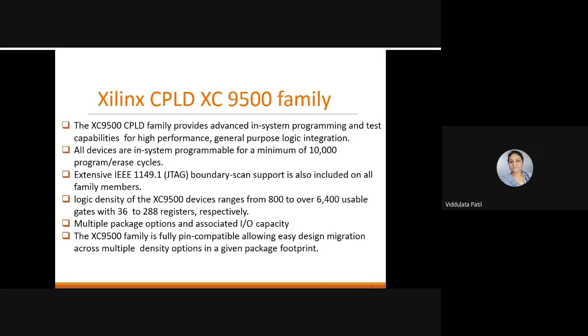This standard is supported by each member of the Xilinx XC9500 family. Because of that, it makes the system cost effective, because it has this testing methodology where we can use JTAG, the Joint Test Action Group IEEE standard, and it strengthens the quality of your product.